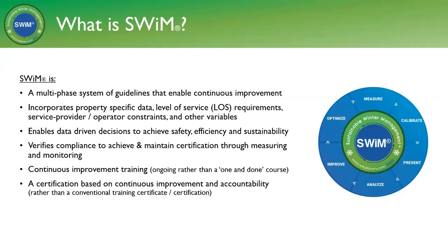And so we incorporate some of what you heard Chris talk about as far as property specific data, or road specific data. We look at salt outputs, we look at level of service being achieved. I thought Chris did a great job of describing the analogy of what we see all the time. If you take a fleet of, let's say, 10 trucks, you'll see some that are applying half of what others are applying, yet achieving the same level of service, yet they don't really realize that that's what's happening in their operations.